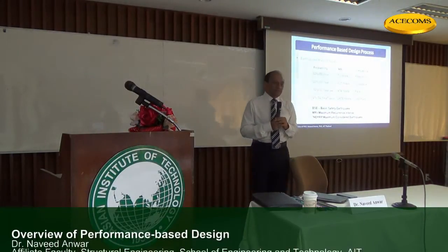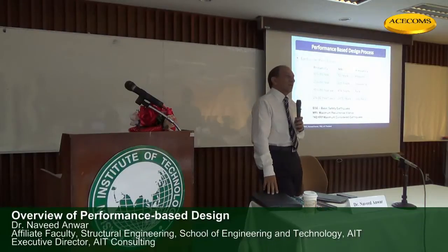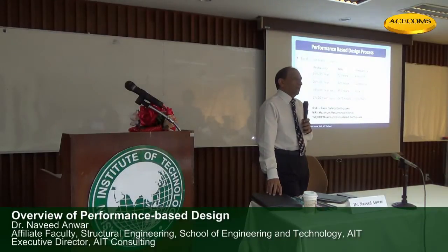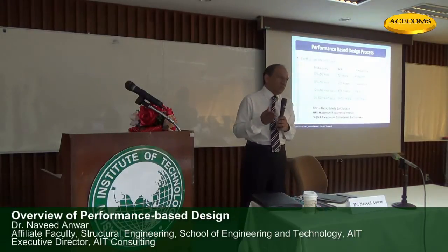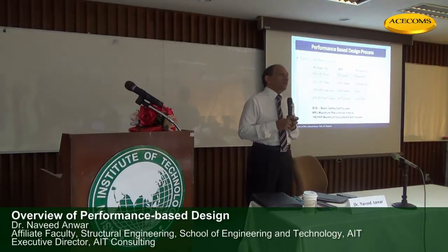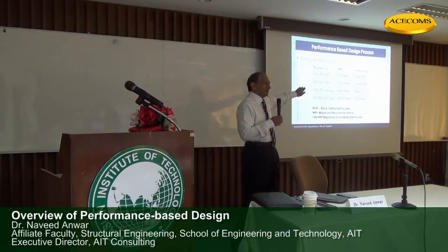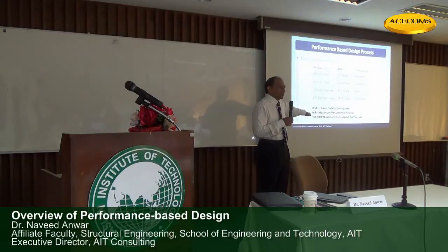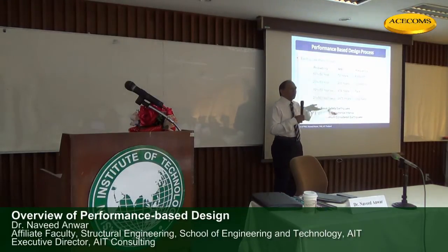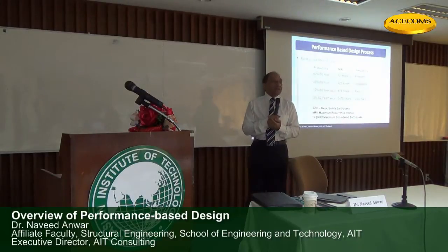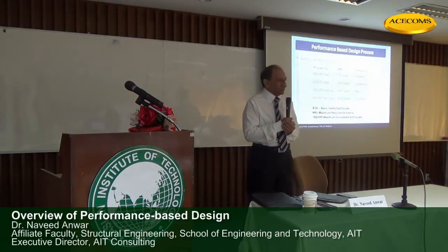Now we can say that I want to design my building for these earthquakes with different performance levels, depending upon what type of structure I'm designing, what is going to be the life of the structure. If the structure is a temporary structure, it's only going to live for 10 years, my definition of the earthquake will change, because 50 years will not come in. 10 years will come in here. So the earthquake level will change because the life of the structure is shorter.